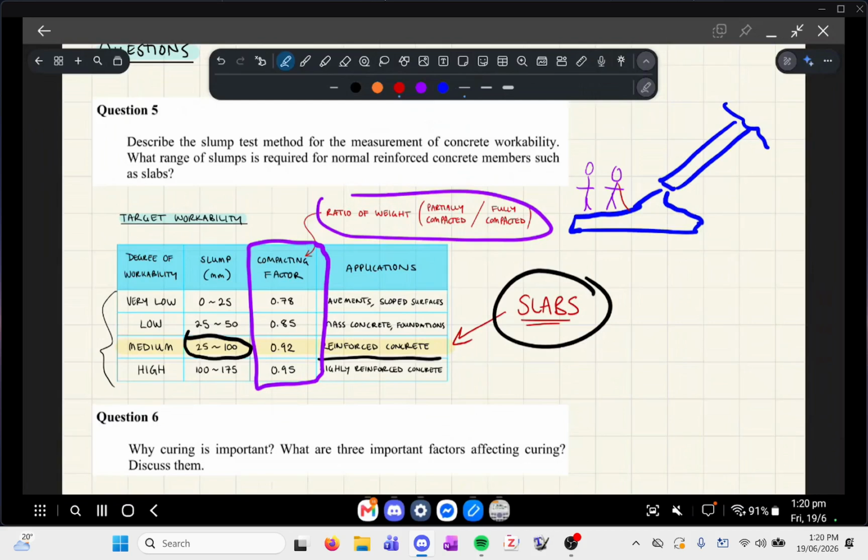That's one thing that it does. These air bubbles get eliminated as you're pouring it, so you have essentially fewer voids in your concrete and it's more solid. But it also increases the workability of the concrete, so it will make the concrete flow more. You don't want to over vibrate the concrete though.